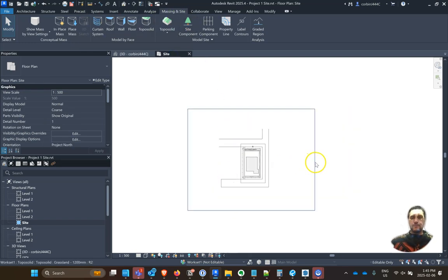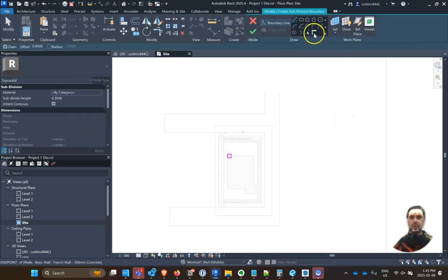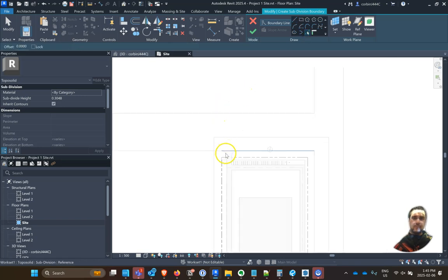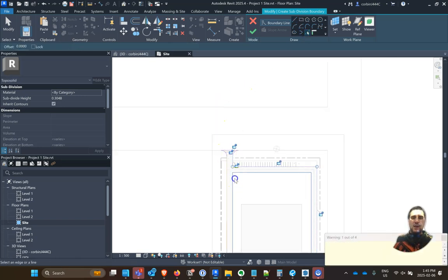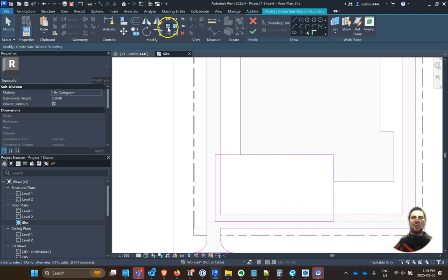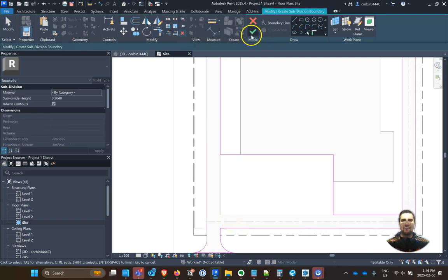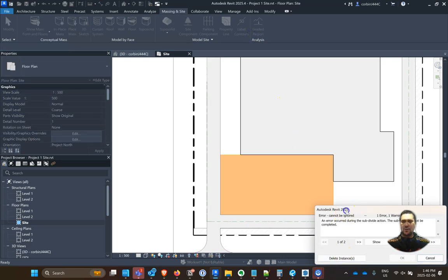Click this. And we'll do our subdivide. And we'll click our pick lines again. The other button that I had troubles with was that it gave us that error message for the surface is too thin. So sometimes I make the bottom layer like 60 or 70 feet, and then you won't get that error message because it'll just cut the topography. So there's that. Delete these lines. Like so. Check mark. And subdivide action.